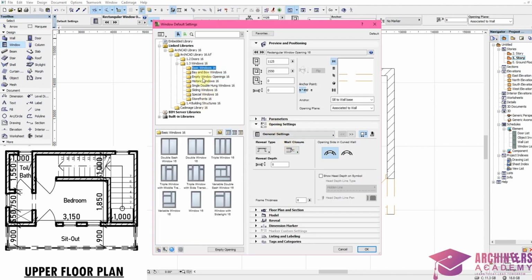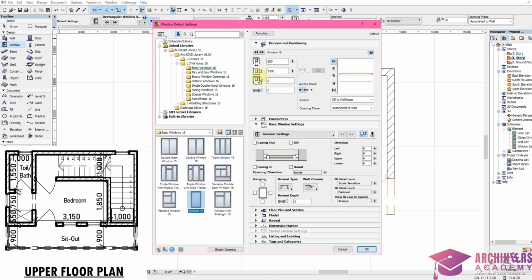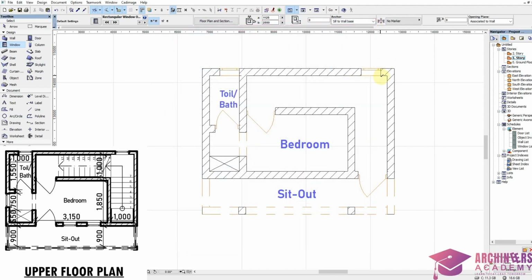So I make use of this same type of windows, but since it's 600, I'll make it of 600 by 152. Let's just duplicate this one right here. Click on alternate key, then we'll duplicate this to be the same window right here. I'll bring one at the edge, make it to be 300 or so.